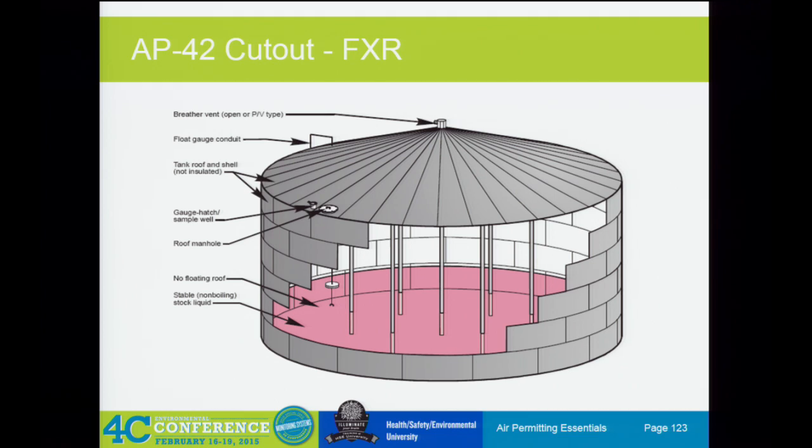Its working loss is when you fill the tank, and the liquid level rises and displaces that vapor out. So the working losses are going to be where your highest hour comes from, and also where the majority of your annual emissions come from. But the breathing losses do contribute, so you have to calculate them both.